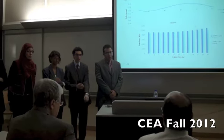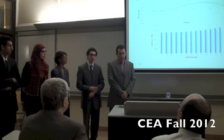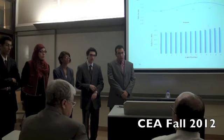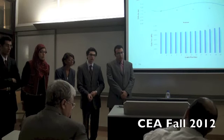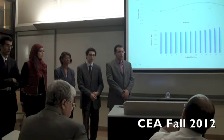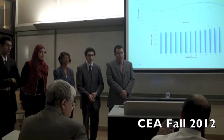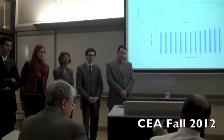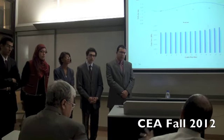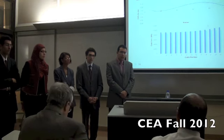Let me rephrase my question. How do you generate the force in the cable? We use the frame elements. And how are these forces generated in the cable? They are pre-tensioned, they are jacked. So in order to generate force, you have to have a deflection, right? Yes, and the force depends on the deflection. So my question stands, can you do a linear analysis? No.